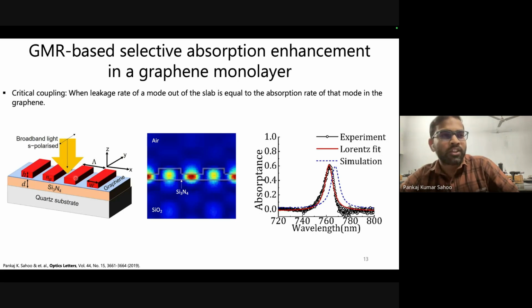But just like a glass surface, most of the light actually gets reflected from the silicon surface. So can we trap the light on the silicon surface? Graphene is used as a trapping material on the silicon surface, so that the maximum of the light falling on the silicon solar cell surface can be trapped, and we can achieve maximum efficiency. So what we do is we use this photonic crystal of GMR or graphene. We put this graphene there.